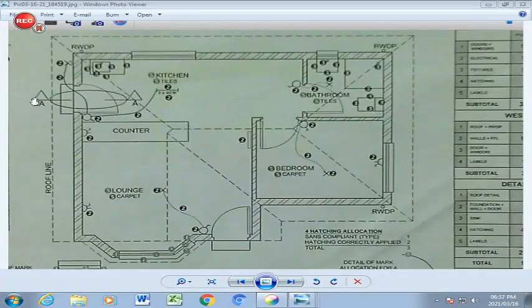The section view, of course, is the cut between this section line here, and you basically standing here and your eyes are viewing in the same direction as the arrow. Remember, you're cutting through a door and the stoop outside, and whatever is in the backdrop here, which is the kitchen sink. So you need to take that into consideration as well. So we're going to draw all the detail that includes that little piece of section there.